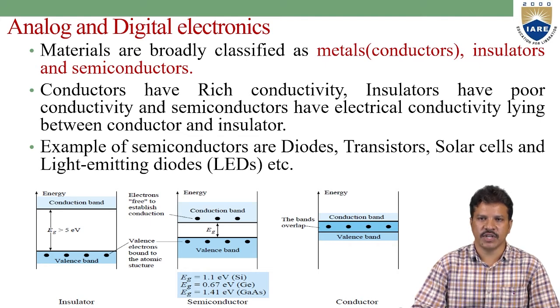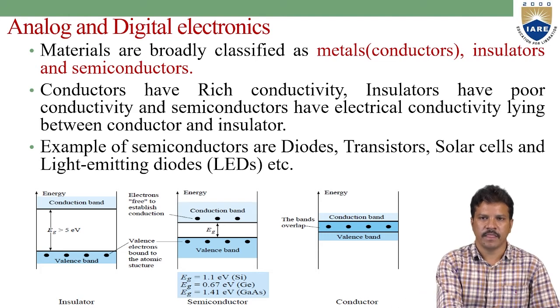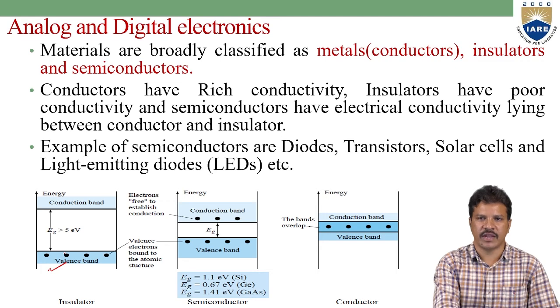First, the insulator. In an insulator, all valence electrons are in the valency band. The energy gap is large, equal to or greater than 5 electron volts. Because of this large gap, even when electrons are excited they are unable to move from the valency band to the conduction band. That's why insulators have poor conductivity.